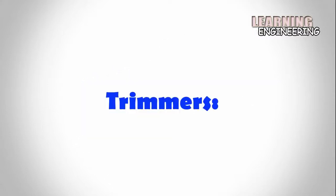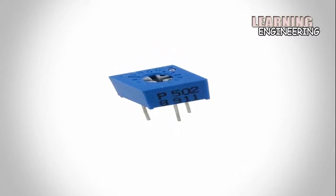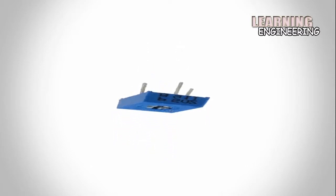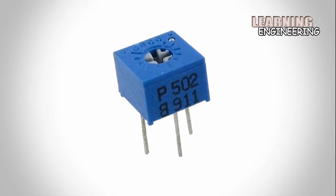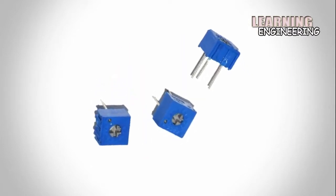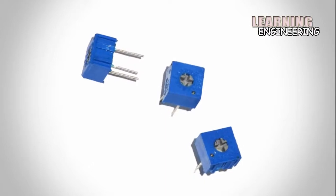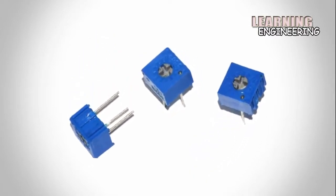Trimmers. There is an additional screw with potentiometers or variable resistors for better efficiency and operation and they are known as trimmers. The value of resistance can be changed by rotating the screw with a small screwdriver. They are made from carbon composition, carbon film, ceramic and wire materials and available in the range of 50 ohms up to 5 mega ohms. The power rating of trimmer potentiometers is from 1/3 to 1/2 watts.